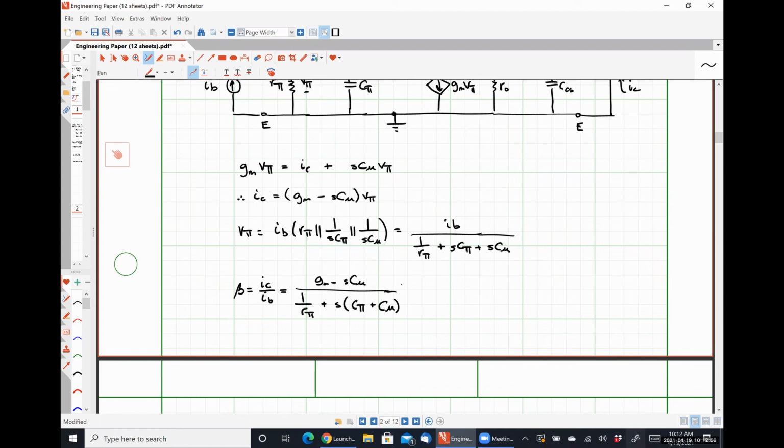All right, so what have typical transconductance values been for the circuits that we've analyzed? Anybody have any idea? Ballpark it. Pardon? 0.2 Siemens. Okay, so somewhere on the order of tens to hundreds of millisiemens, right? Okay, or milliamps per volt.